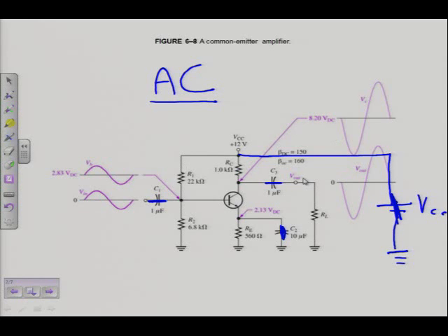Alright, now I have to simplify the circuit so that I can see which of these resistors are in parallel and which are in series. Of course, I have to do some calculations about these resistances. The easiest way to approach this is with the 3 terminals of the transistor. So let's start with the base. And I can see here at the base, from the base R2 is connected to ground.